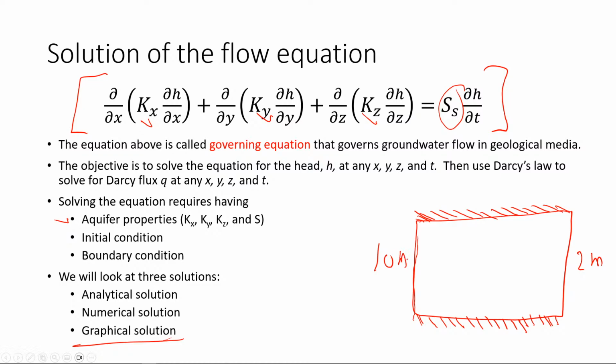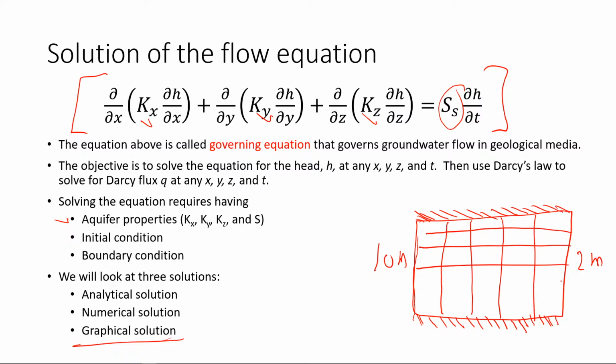Numerical solution is that you don't get an exact solution, you get an approximate solution over a discretized area. So to get a numerical solution, you need to discretize your model domain into cells or elements. If you are doing finite difference, that would be cells, for example. If you are doing finite elements, that would be different elements, yeah? And then I will tell you what the temperature would be here, or here, or here. You just find the temperature in this cell, yeah?